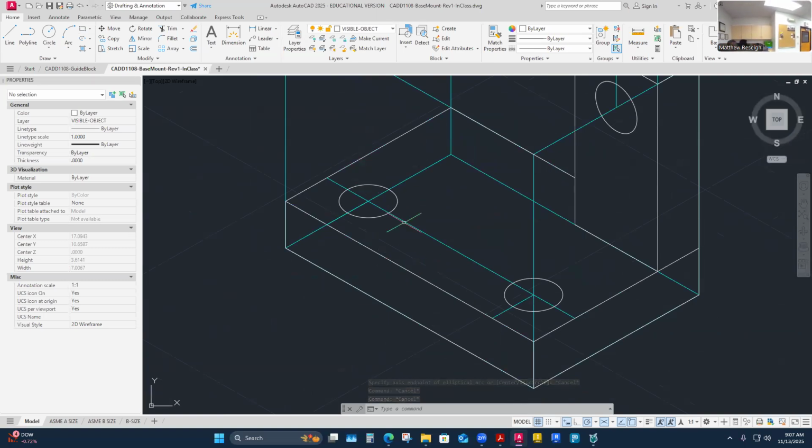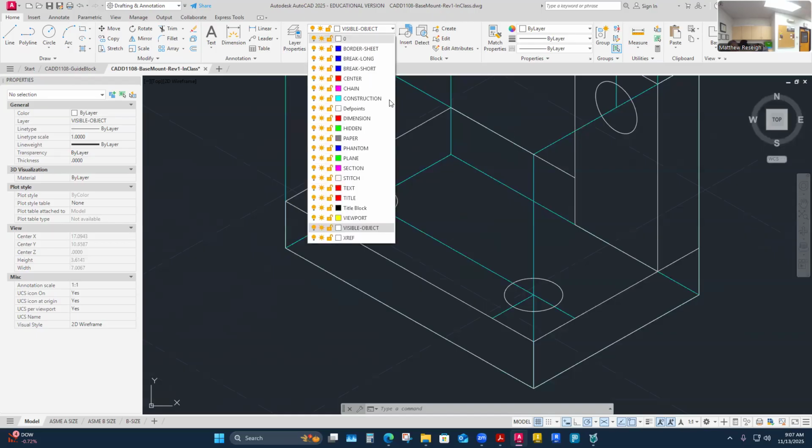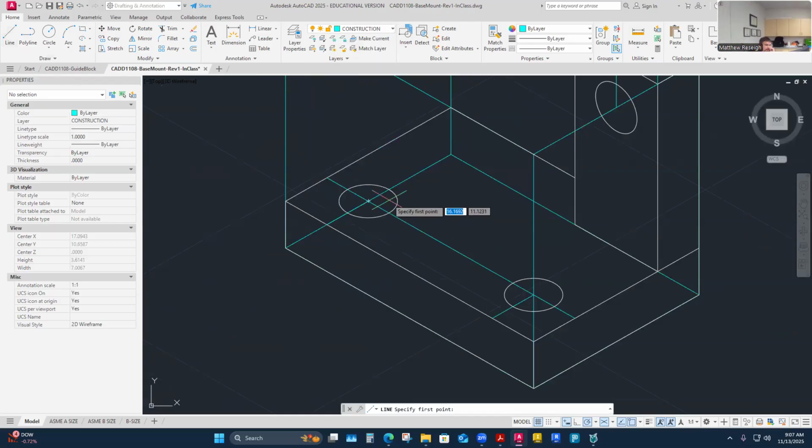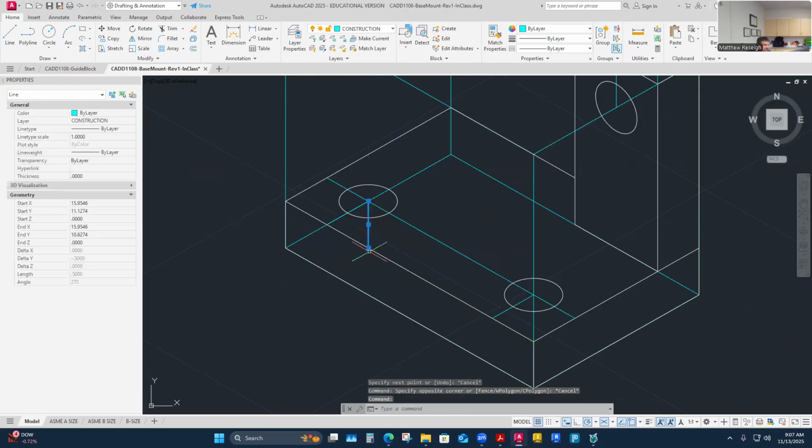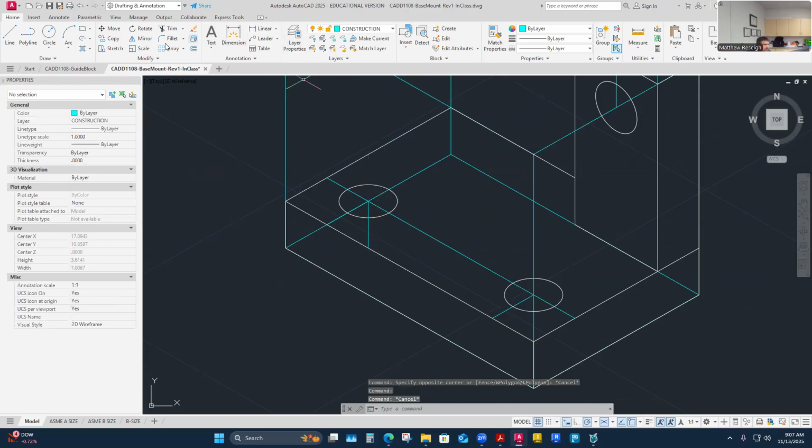I also want to make sure where the exits of those are too, and there are ways I could look at that. It would be from center down like a 1/2 inch. This is a 1/2 inch thick plate. That is the exit of that hole going down through. If I was to do a copy of this, I'm just checking it myself. This is where the hole would exit through the bottom plate, and you wouldn't see any of it through the top hole again. The thickness of that plate is making it so nothing is showing up. You won't see the exit at all, so I can eliminate that. I don't need that. That's just a little check there. So these both fall into that category.